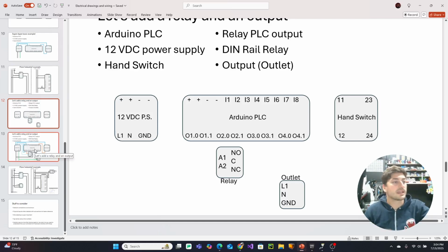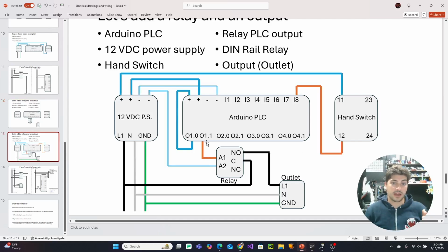So let's take a look at the hobby version of this circuit now, okay? And let's walk through all the wires that have been added. I also put in one new color convention, which is a wire that ties directly into the PLC. I've changed to orange, where in the previous example I just left it as blue. So basically the final PLC signal wire is orange.